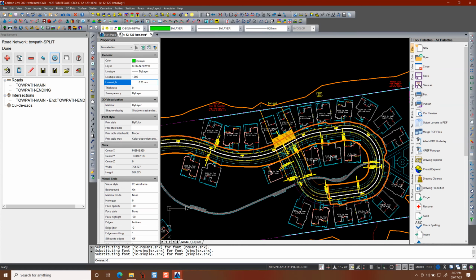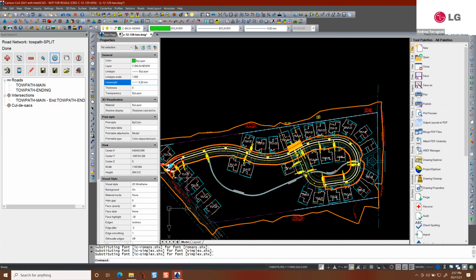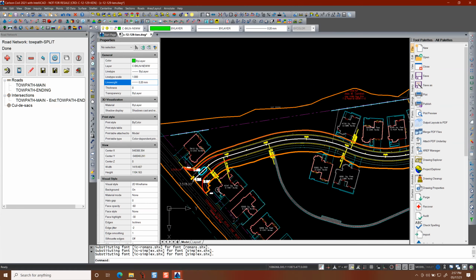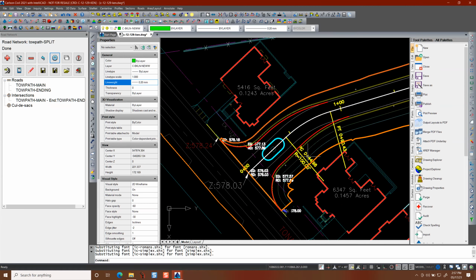that was done, sort of a shrink wrap. It's looking only along that last edge, that last outermost edge. And again, if this wasn't curved, if it came in straight, it would start at the center line, go to the edge of the pavement, go to the sidewalk, and catch the slope, and that point happens to be lined up with zero, same thing over here, and so it would correctly grab everything around our set of 3D lines.